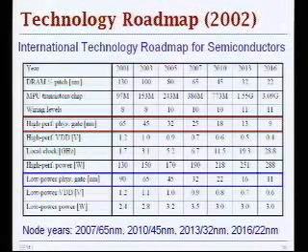Now, for portable devices, there is no way you can sustain these power levels. You would have to carry maybe 50 pounds of batteries in your bag and have a little phone that you can use to talk. As I said, the mobile phone industry has predominantly been defining this low power scaling trend, and the main requirement there is to keep the power constant. The reason you want to keep the power constant is that you want to keep the battery size the same, because the energy capacity of the battery hasn't improved much over the years, and until that problem gets solved, we have to stick with constant power.